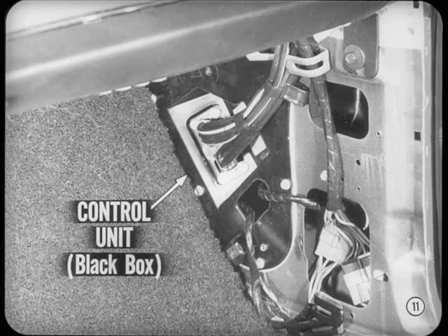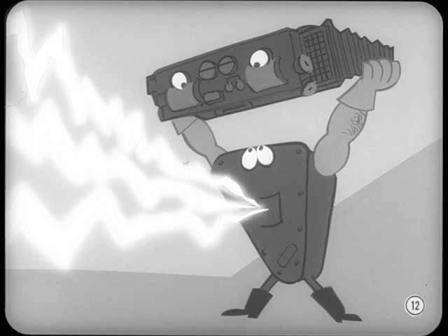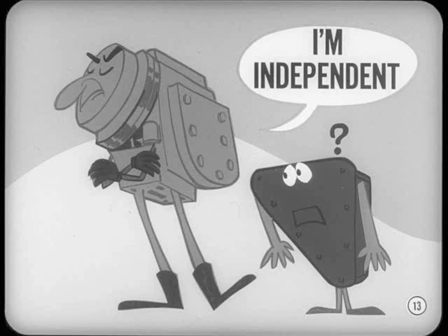The signals from these 3 conditions are transmitted to a black box-type control unit located behind the right-hand side cowl trim panel. Inside the control unit, the 3 signals are translated into work orders, which are directed to the various air distribution doors, the water valve, and the blower speed selector inside the control unit itself. The air conditioning compressor clutch is engaged whenever any of the instrument panel push buttons is pressed, except the off button, if the outside temperature is above 32 degrees. The electrical circuit for the clutch is independent of the control unit, so it does not respond to any signals from the sensors or the thumb wheel.